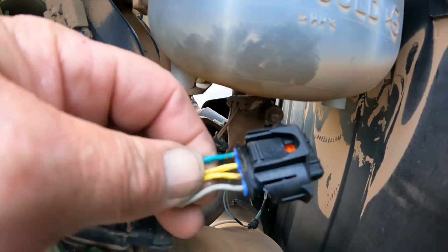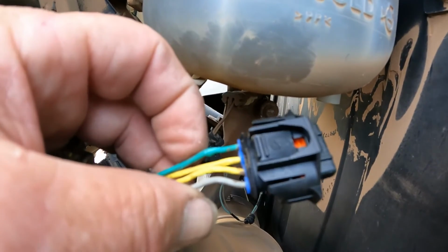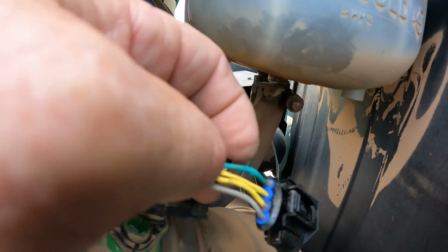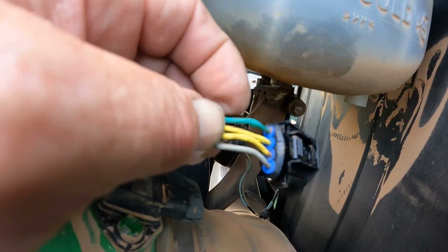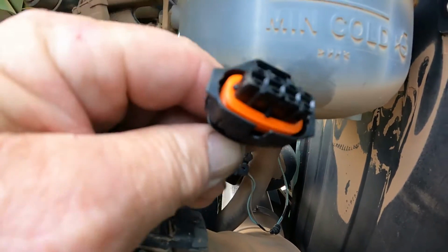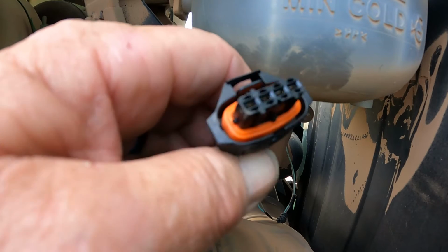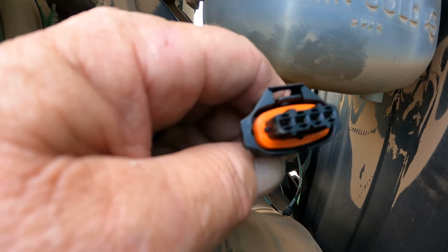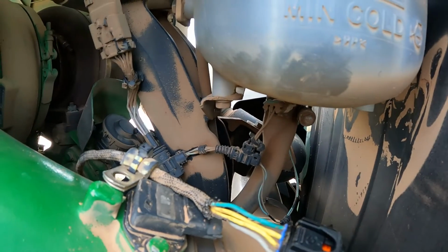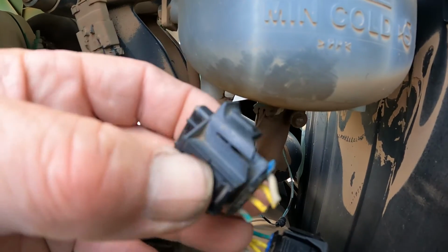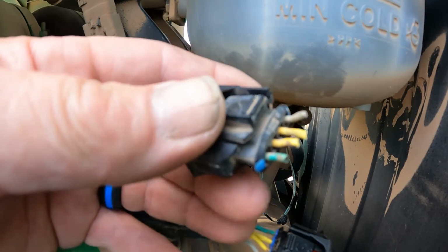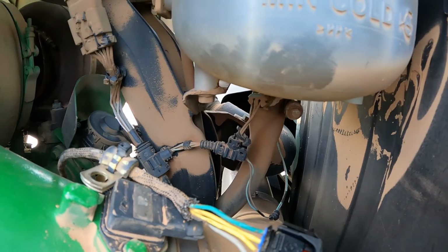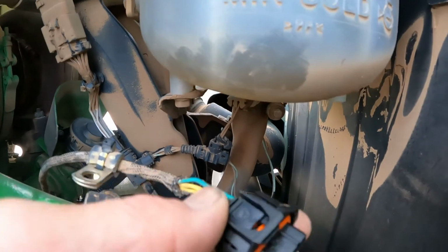This is what it looks like after you've repaired that plug and installed all of your new wires. You can see I've got a pretty good seal on the back side where my seals are fitting up into the cavity of the connector, okay? And I made sure that I pushed all of my terminals in deep enough that they did click into place and lock into place, okay? This is the old connector here, okay? So I just left all the wires in there and cut them one at a time, crimped my new terminals on, and installed them in my new connector housing, okay?